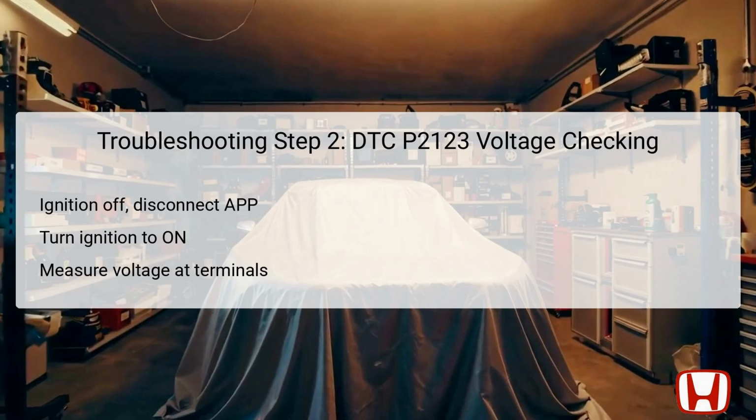If it does, this indicates that the power supply is adequate and leads to the next step in the diagnosis. If the voltage does not meet this criterion, further investigation is warranted, as it may suggest a fault either in the power supply line or within the ECM. Each measurement needs to be precise, as inconsistent readings can mislead the diagnostic process.